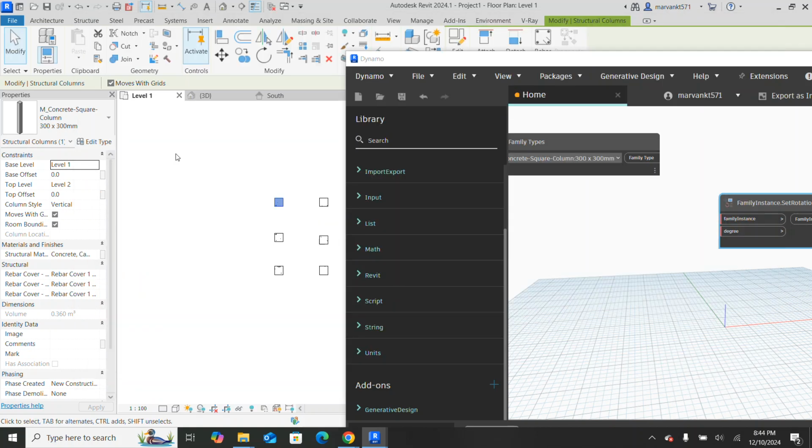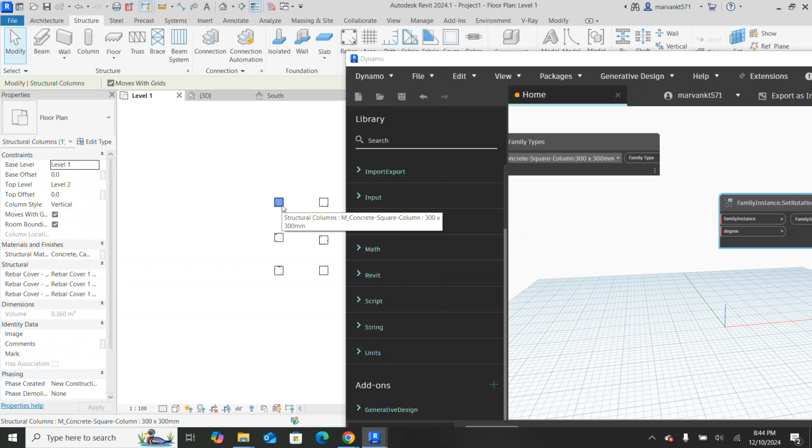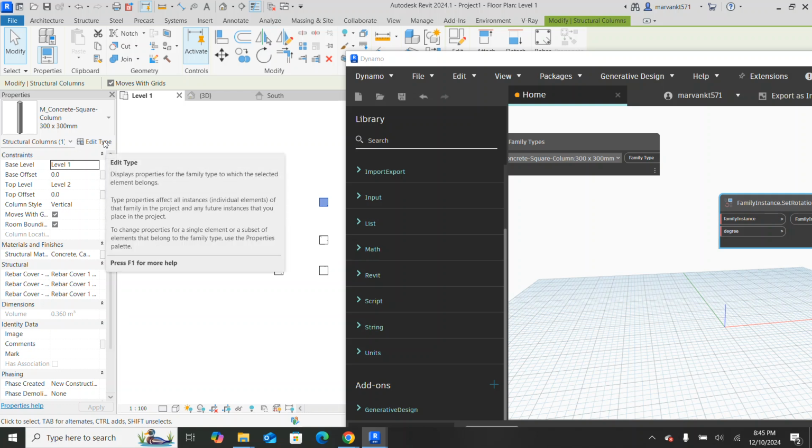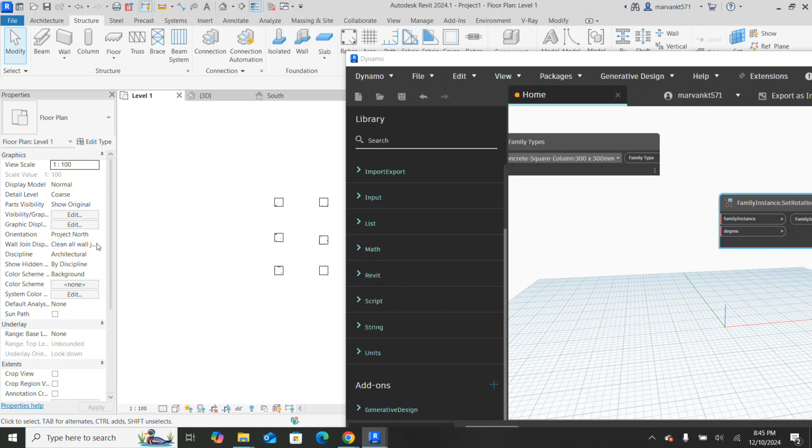Correct? Yes. But if I wanted to change them one by one, then I have to do the duplicate for everything, and then you can consider each a different instance, in case you want to give a different color value. That means here I need 300, here I need 500. Where you want the 500, you have to do edit, duplicate. But there is another method, you can consider an instance parameter, then you feed the instance parameter.